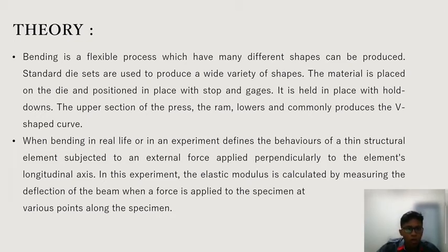So next, bending in real life and in an experiment defines the behavior of a thin structural element subjected to an external force applied perpendicular to the element's longitudinal axis. In this experiment, the elastic modulus is calculated by measuring the deflection of the beam when force is applied to the specimen at various points along the specimen.